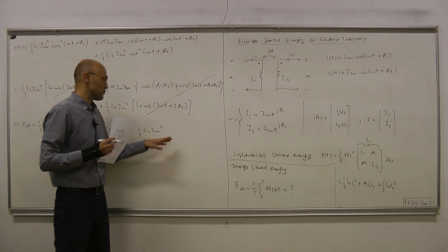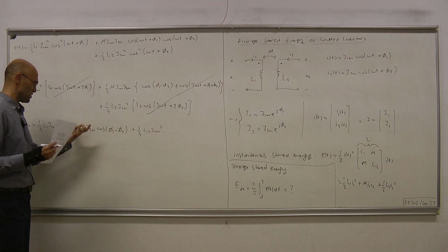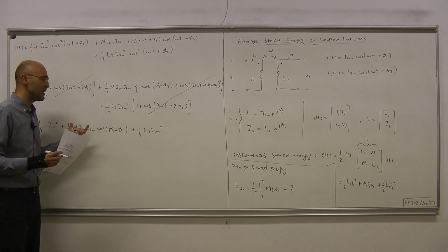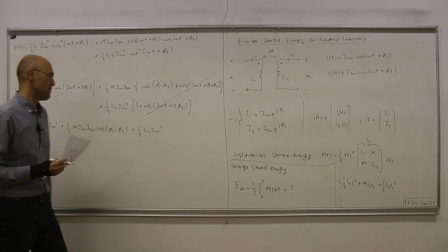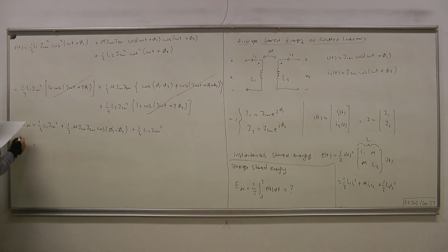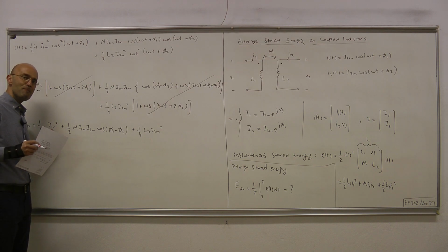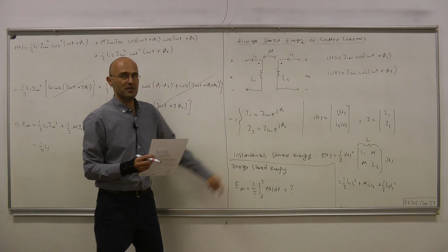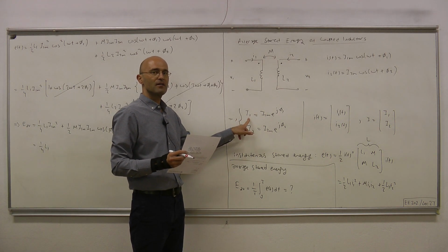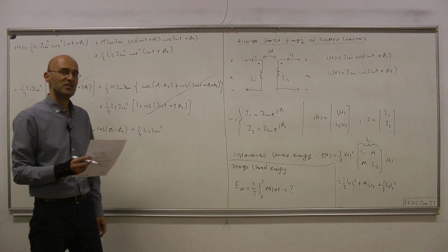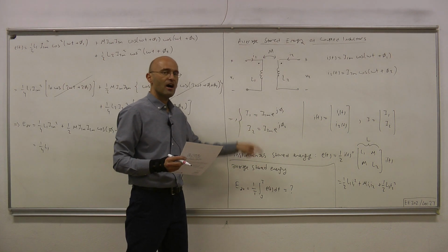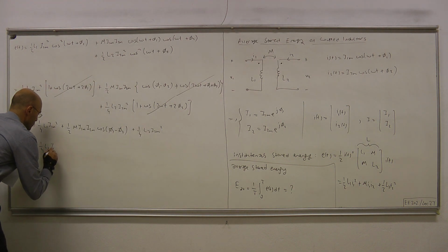That's the answer. In a sense we can stop here, but let's not, because this looks a little bit complicated. It turns out that by looking at this expression in a slightly different way, we can put it in a form that's very elegant and easy to remember. So we first write 1/4 L1. Now here we have I1 magnitude square, the magnitude of this phasor or complex number. What's the magnitude of a complex number? You take the product of that complex number with its complex conjugate and then take the square root. Since we already have squaring here, magnitude square equals I1 times I1 conjugate. So let's write it in that way.